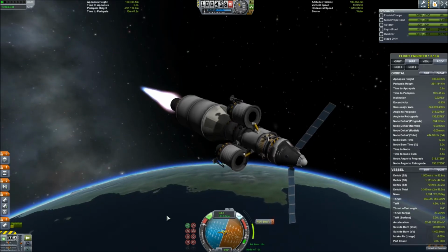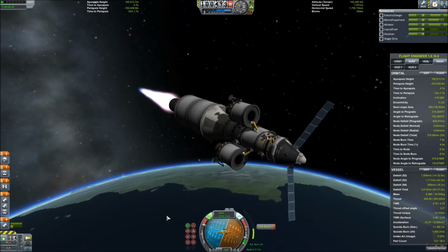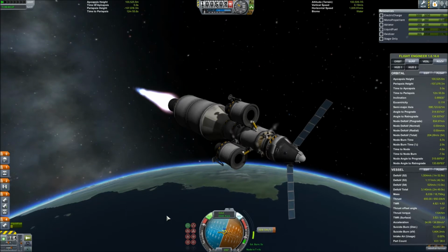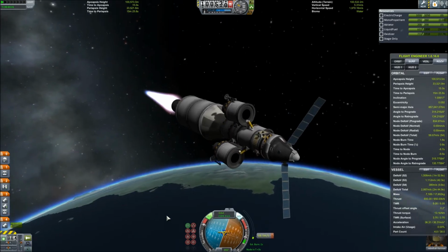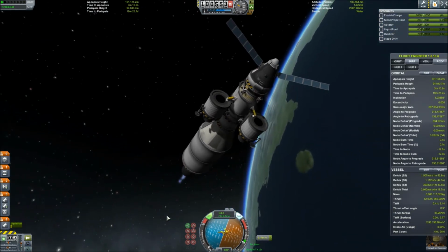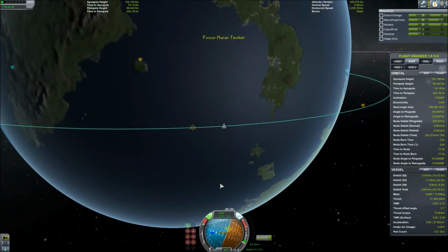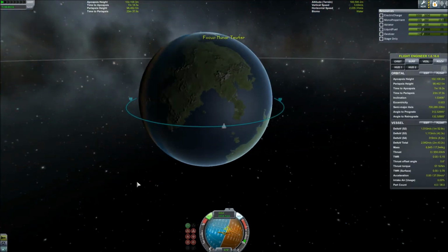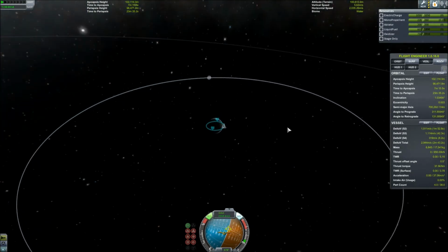As soon as we hit 15 seconds before our burn time, that is T time, whatever it is, we initiate our burn. That's a 30-second burn. You can see we began it 15 seconds prior to T, and it completed almost exactly 15 seconds after T. And we go to check our circularization, and sure enough, we are circularized right around 100 kilometers above the surface of Kerbin, just as we intended.